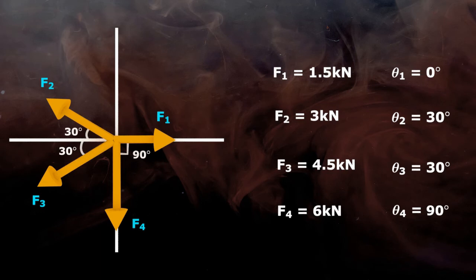As we already discussed, there are two analytical methods to find the resultant force acting on a body, out of which the law of parallelogram can be used only if two forces are acting on the body. As the number of forces is more than two in our case, we will solve the numerical using the method of projections only. So the first step in this method is to resolve each force into two components, one along the x-axis and another one along the y-axis.